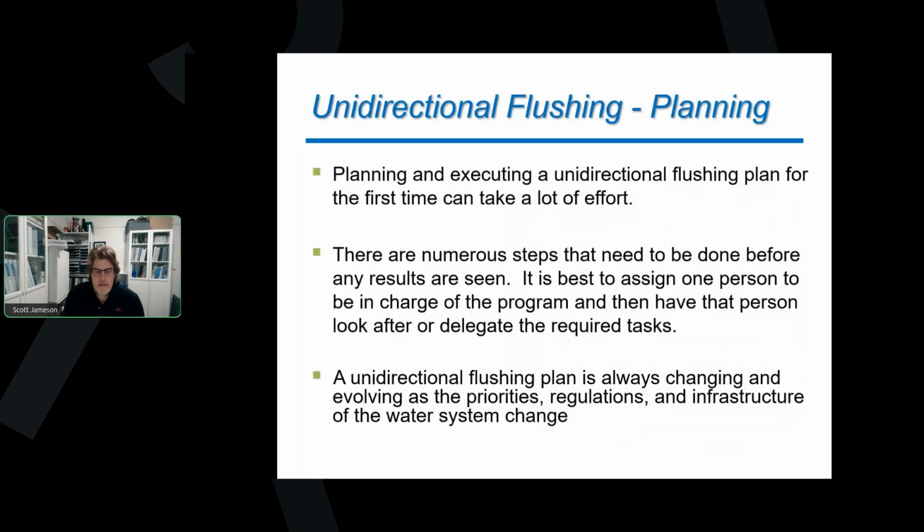So we've got to start taking our flushing program and changing it into a UDF. This can take some time, can take some effort if it's the first time you're going through it. Maybe some of you have an old system that someone else did and you're just looking to upgrade it. But if you're just starting out from scratch, you've got to be willing to spend some time and effort at the desk first and do some planning to make sure that this is going to be effective for us.